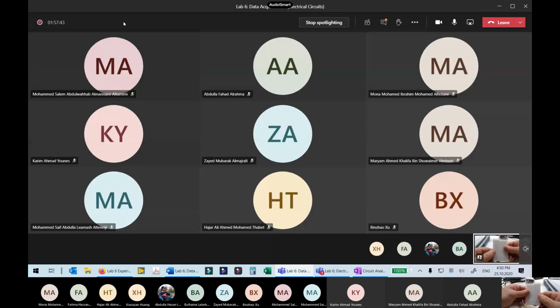The benefit is that you can connect circuits by mechanically connecting them to these terminals on the breadboard. If you solder any element, it is permanent and you cannot disconnect it. So breadboards give you the choice to avoid soldering.